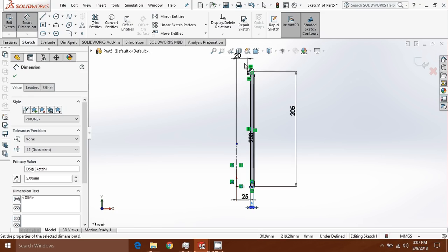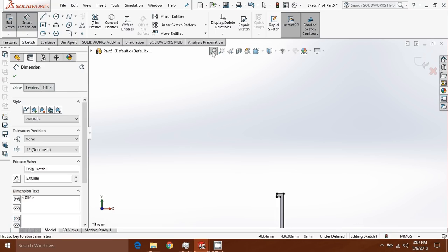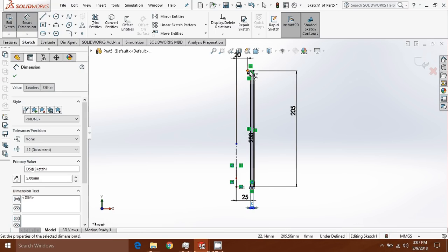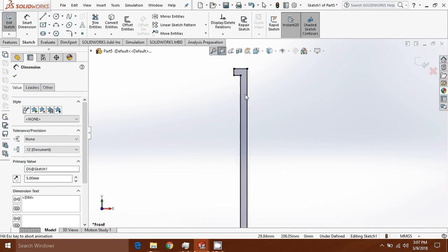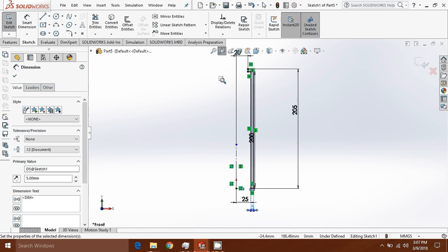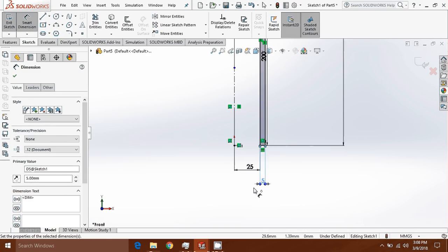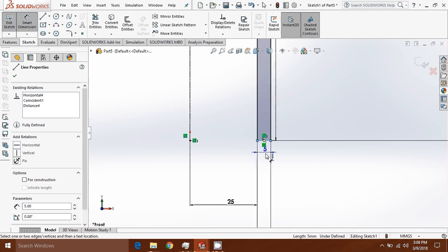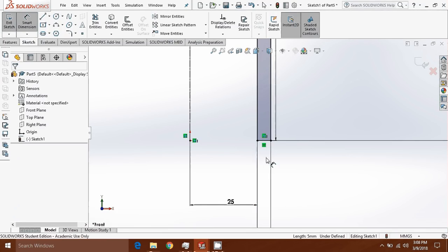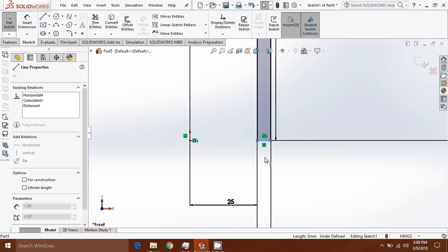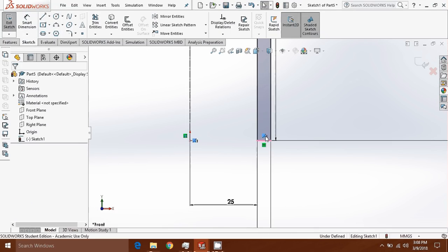Now, one thing I caution you when you're building these kinds of multiple rectangle shapes, because you could build this with just a simple rectangle up top here. I'll show you what I mean. You could build a rectangle here and then create a long rectangle there. The only issue with that is that if you don't clean up your overlapping lines, you're going to have an issue where it might say that your path is not continuous when you go to create an extrusion. You might just have all kinds of errors based on the fact that you have overlapping lines. Let's delete that there.